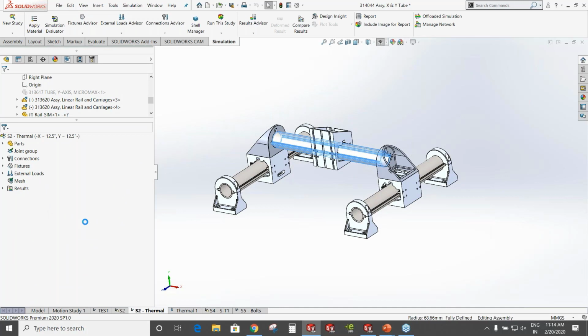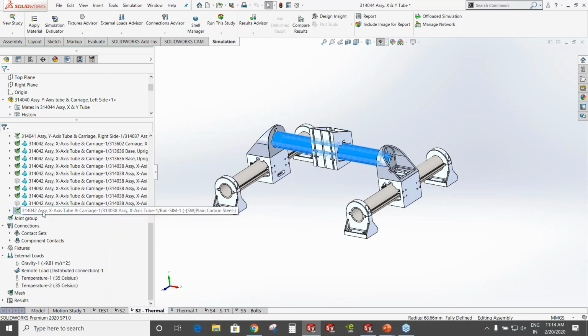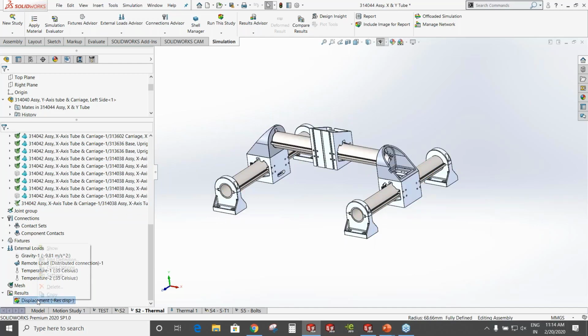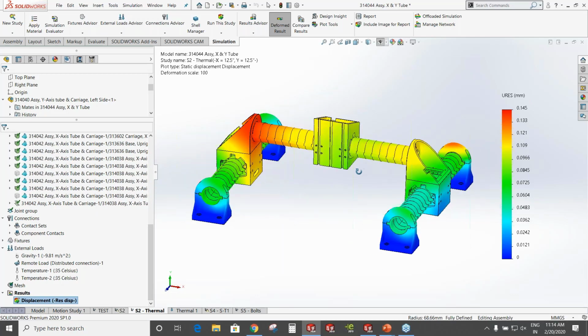Another thing, these beam elements, as per your requirement, you can also use to predict shear force and bending moment diagrams. We can combine these beam elements and get the results in the form of shear force and bending moment diagrams. What you're seeing here on the beam elements, the temperature has been applied, and you can easily get the results. Due to the thermal load, it can have displacement variations. It can also have a temperature distribution change. All these you can easily see on the beam elements also.